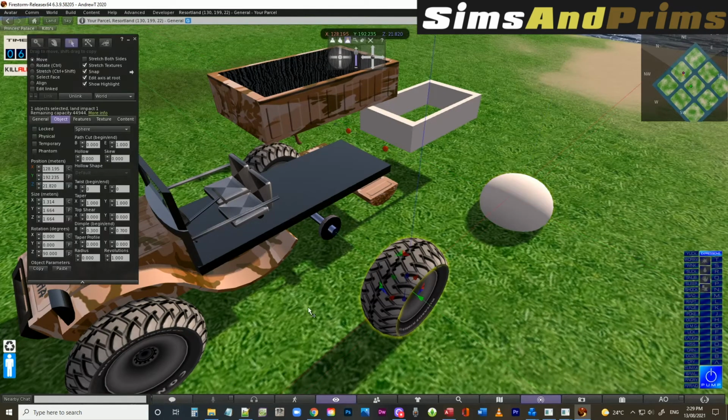Okay, and that is 0, 0, 90. We'll make that the same. It should be 0, 0, 90. Okay, and this says it has a dimple of 0.3 and 0.7. So we'll go in here, change that to 0.3. And that one to 0.7, and voila.